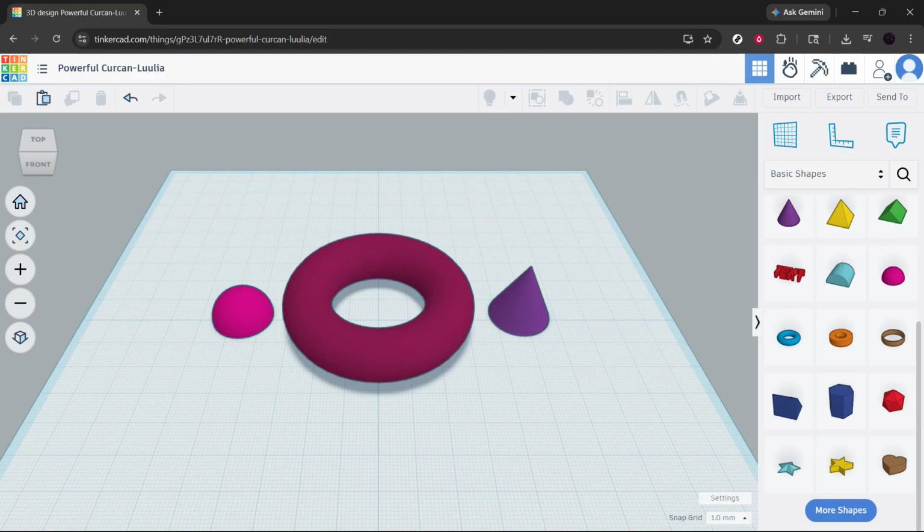First, it's important to understand one thing right away. If you export as STL, your color will not carry over. That format is mainly for 3D printing, and it only stores the shape of your model, not the color information. So if your goal is to keep the colors visible in another app, a viewer, or a presentation, you need to choose a different export option.